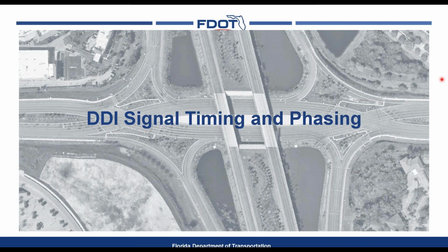conflicts is because in a traditional diamond, that movement is available. Traffic can get off the freeway. They can actually go all the way through and get back on the freeway at that location. So for that reason, those conflict points do exist. While they're not common, they are there. Whereas in a DDI, that movement is not available. As you see on the screen right there, to simply exit the freeway and then cut all the way through the arterial and back on the freeway is not a viable option with the DDI. So hope that answers your question, John. And Randy, go ahead and keep going, please.